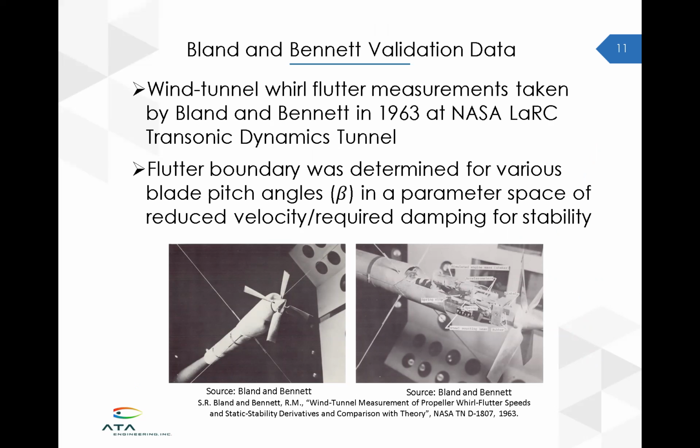And so they did this study varying the free stream velocity and looking at different damping parameters, keeping the stiffness of the pitch and yaw motion springs constant, but changing the damping value, since damping is the primary thing that influences stability. And they also looked at several different pitch angles for the blades.